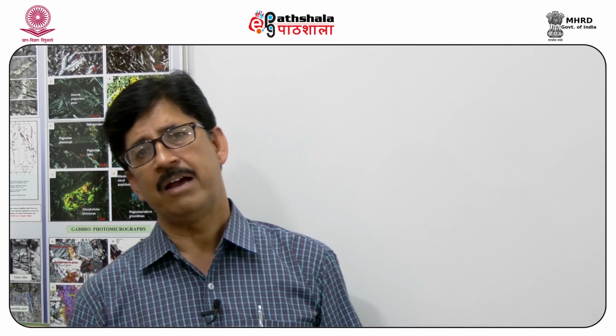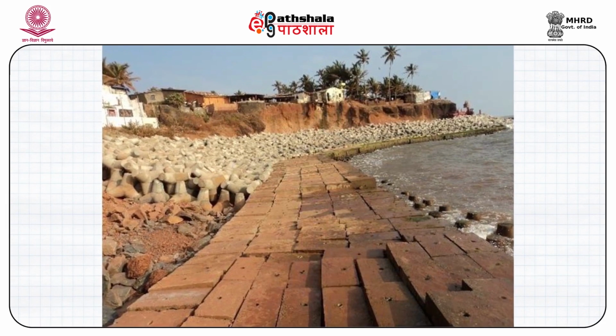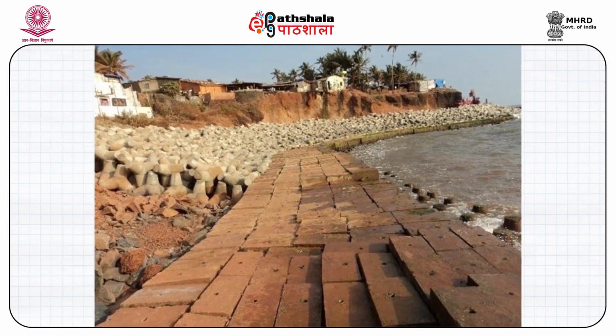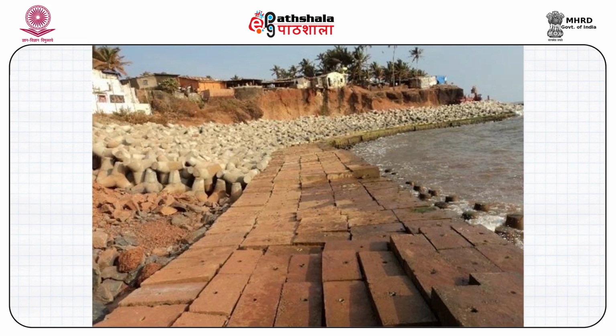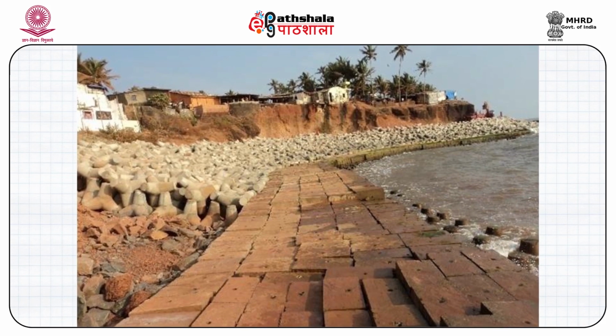Apart from this, coastal areas are continuously subjected to storms and sometimes tsunamis. For this, we have to make some defenses. The defenses which are usually used are either laying of riprap, rock pieces or rock boulders along the coast, or installation of concrete blocks with tripods or tetrapods, concrete tripods and tetrapods.